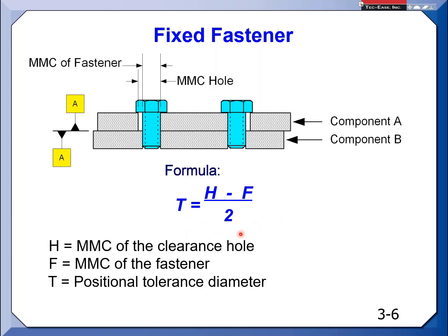So what typically happens, what does engineering start with? Well, they have a requirement, the mechanical joint must be. They usually will pick the fastener first based on a requirement, like maybe shear, compression, or torsion, based on some design requirement, and that's how they'll decide how big the fastener needs to be first, typically, if it's a new design. Then based on that, what would be the appropriate clearance hole relative to the fastener? And then for this number down here to derive your tolerance, it becomes a question of, based on the process that's going to make all these features, what is the capability? So there's a little bit more going on with this formula. This is just showing you some mathematical formulas. There's a lot more going on with engineering, making decisions about these contributors in the sandbox based on a design intent, based on a system requirement.